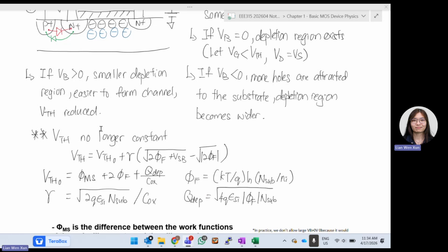in normal case, when there's depletion region, and then when this upper part, the gate will pull some of the current. So when gate voltage is high, maybe 1 volt, it will help to attract all the electrons over here to the top. That's the normal case. Okay. Here, although we know there's depletion region, it will stop a little bit, but it will still attract up. But if now VB more than 0,